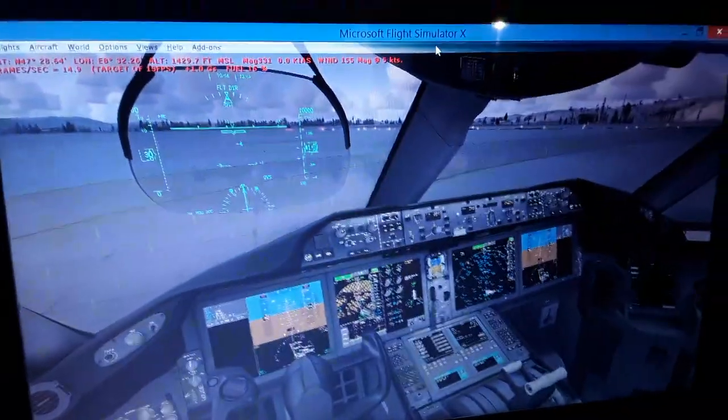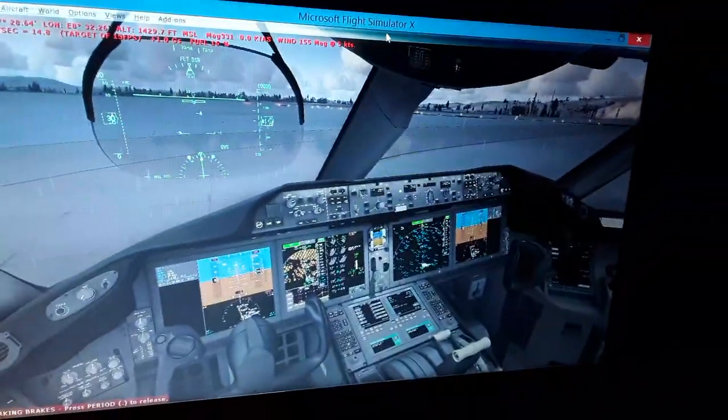For approach and landing, we're gonna have full flaps, 25 degrees or 30 degrees, and also a pitch attitude of about 9 degrees or less at touchdown, also for takeoff. And we're gonna use 145, 150 knots or higher, maybe 160 knots airspeed with wind correction, because we have some side wind. We're gonna use higher speed for approach and landing and also for takeoff. So we're gonna have all these things.